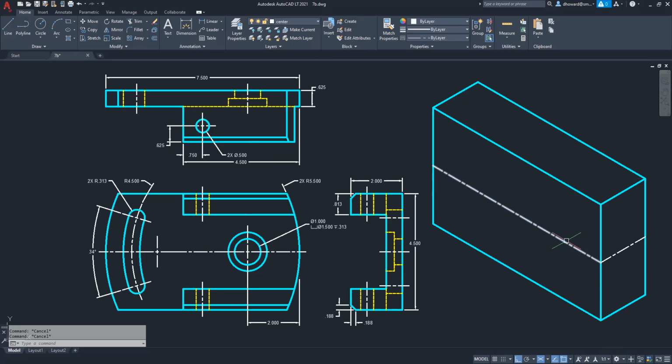So the sides, these sides right here, are 0.813 thick, okay, which is 13/16. So I can come down that distance. I think that's what I'll do. Get my line here. Click on that corner and pull down 0.813. I'm just going to use decimals from here on out since I know what they are. 0.813. And then over. Just hang off the edge there.